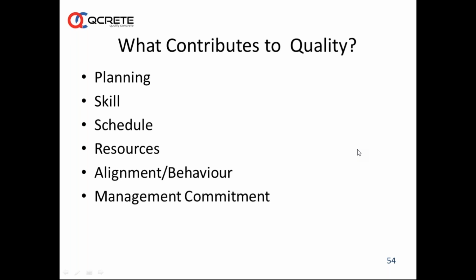Vishweshwarya Sulikeri is asking another question. What is the difference between FRC and general reinforced concrete? When we are using fiber reinforced concrete, the fibers can be an additional reinforcement. You have polyester fibers or steel fibers. These fibers are added as extra in the RCC structure, to control plastic shrinkage and settlement cracks, to increase the abrasion resistance, impact resistance, fatigue resistance, and to also increase or maintain the fire rating. Fire rating is said to be better.